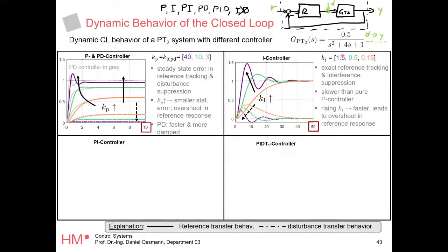However, the control gains are much, much lower. See, we've got 40 here, here's the maximum 1.5, and with a maximum of 1.5, we are very much overshooting already, very much oscillating. So there's a hard limitation on this control gain because we're adding too much lag in our system by that integral. And you see that here, the time scale now is 5 times higher than we have with a pure proportional controller. And this is why pure integral controllers are rarely used, because they are so slow. They are slowing down your system.